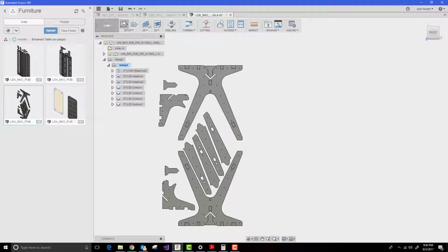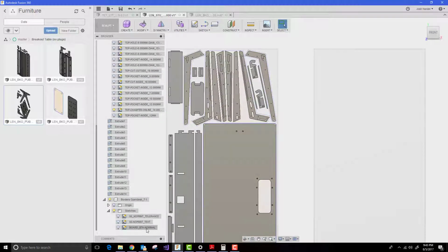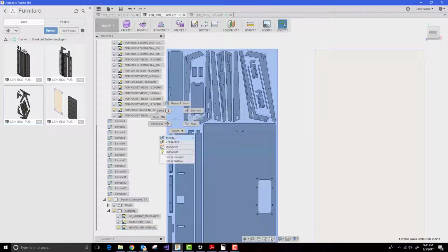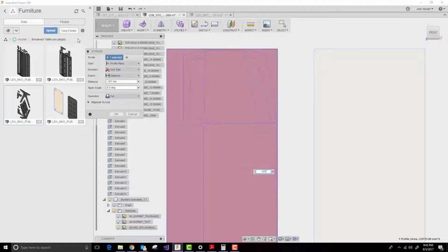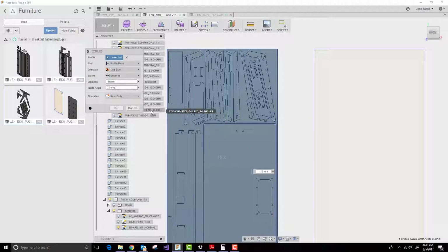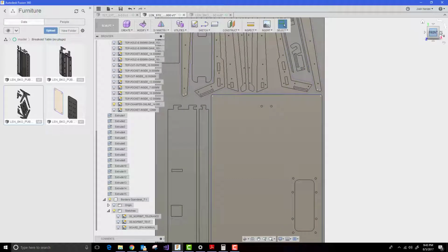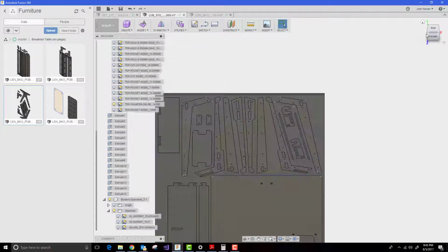Now, with my setup, I mentioned that I'll leave that one thing open. Let's go back to this guy. So one thing I forgot to mention. I'll go back and I will take this board here, and I will go ahead and extrude him -18 millimeters, and I will do him as a new body. So why am I doing a new body, -18 millimeters? Well, one, that body ends up being right with everything else, which is nice. But why is it nice?